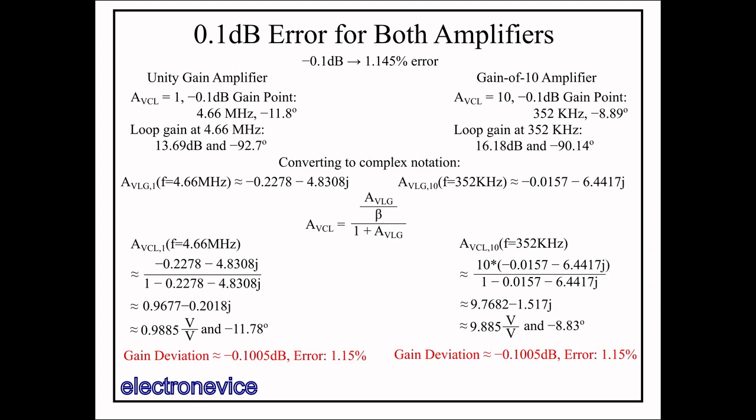If your circuit is sensitive to phase deviations, then you'll need to make sure the bandwidth is higher to ensure that in your pass band, the phase shift is at an acceptable level. And to determine what the phase shift will be, it's best to test or simulate rather than to do straight analysis, as the phase is highly dependent upon the locations of the poles and zeros in the specific op-amp's open-loop transfer function, and computing the locations of the poles and zeros of the closed-loop transfer function is not trivial.